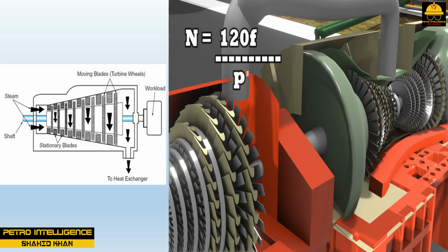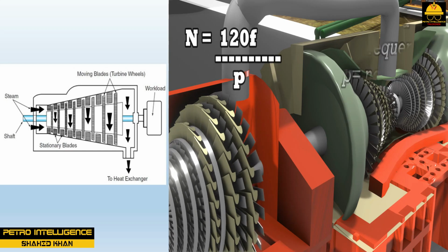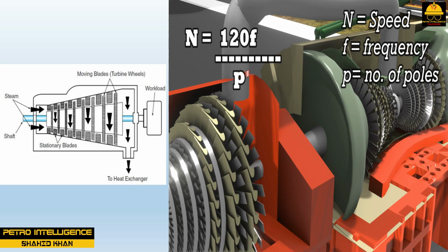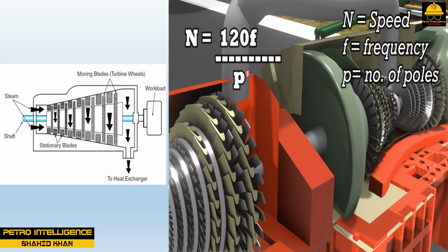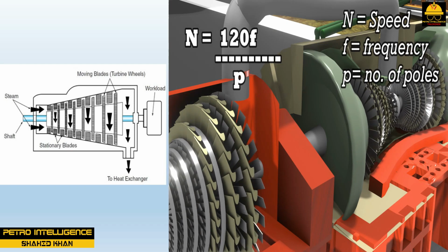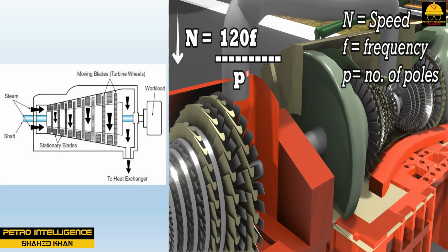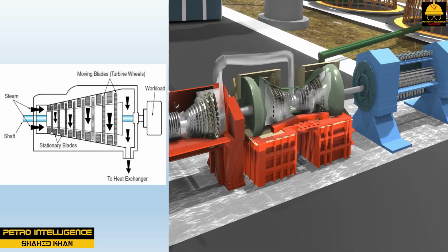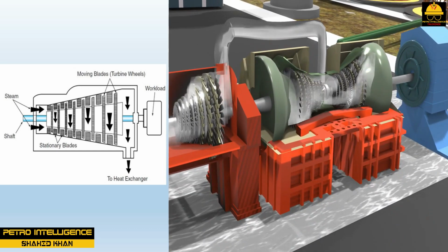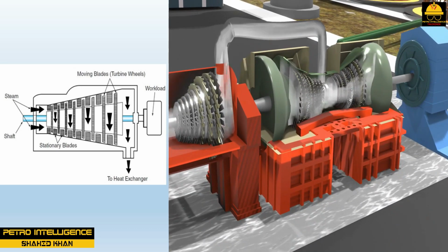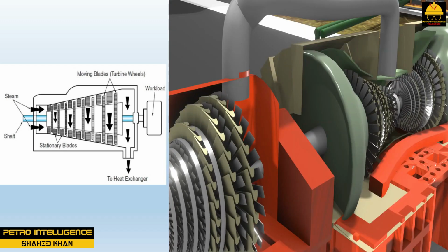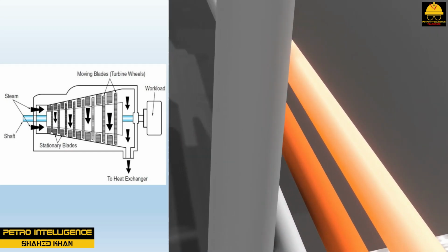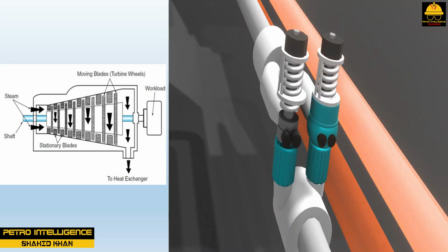Non-condensing or extraction type turbines are multi-stage turbines designed to take high-pressure steam, use it in the turbine, and then extract a portion of the steam for other use. As high-pressure, high-velocity steam passes over the turbine wheel, the steam expands. This expansion enables the turbine to divert low-pressure steam to other units. Some multi-stage turbines can induce steam into back stages to increase delivered horsepower. They are called induction-type turbines.